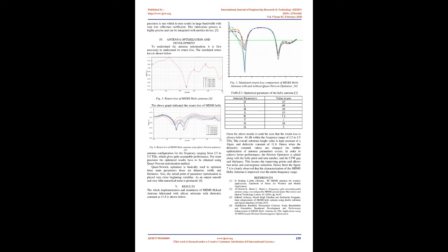The fabrication is done using the process called focused ion beam, FIB, in which a highly focused beam, such as a Ga+ beam, scans and cuts the substrate surface inside the vacuum chamber. This FIB process gives a great flexibility in micro-scale measurements. Similarly, the 3D configuration is introduced for the CPW feed. Fig. 2. CPW feed 3D configuration.